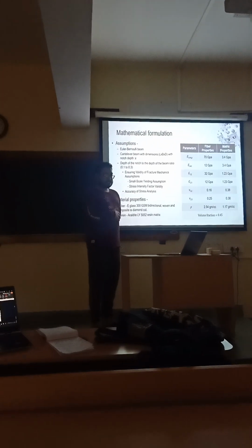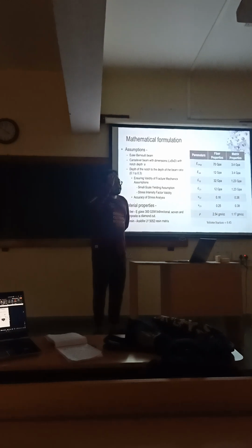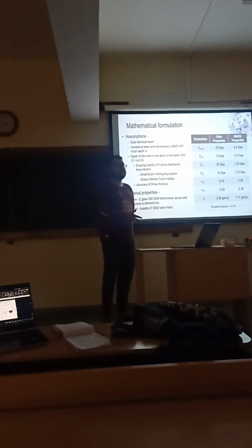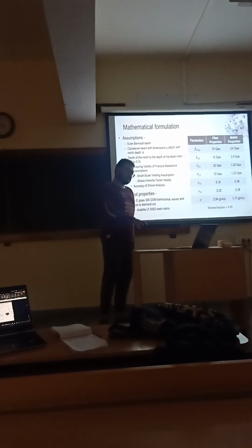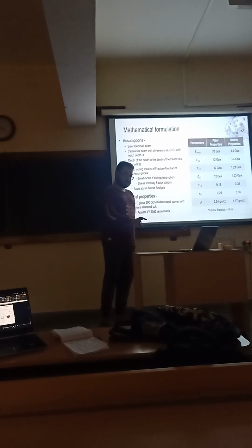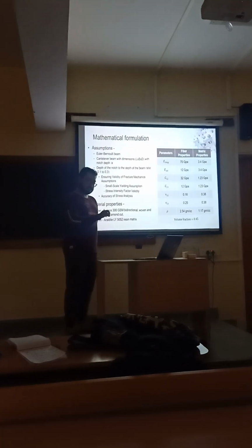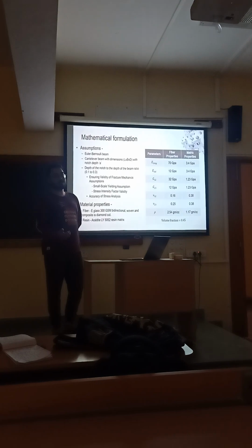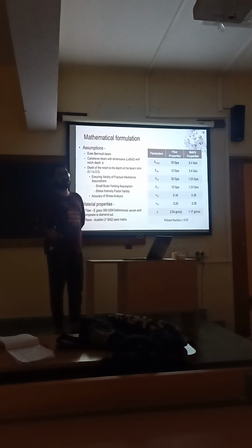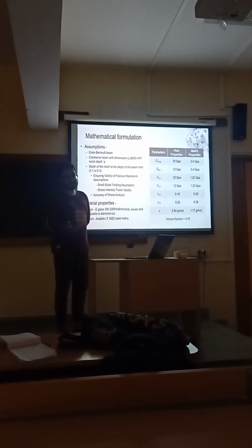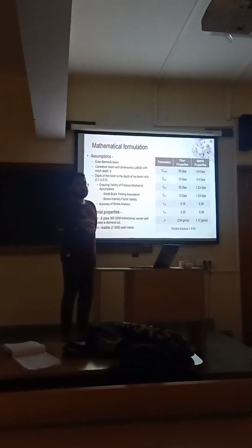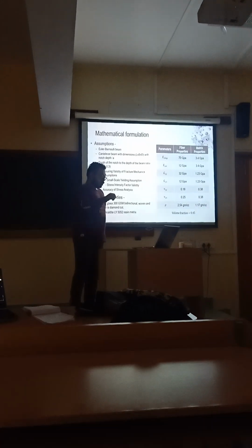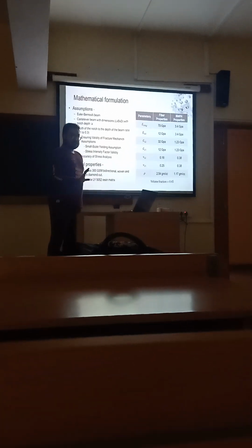And the second thing is the stress intensity factor. The stress intensity factor generally works in this range only. When we are talking about linear elastic fracture mechanics, the stress intensity factor concept is valid only in this framework. If we shift to elastomeric concepts or viscoplastic or viscoelastic materials, there is no such concept of stress intensity factor, because they talk about strain rates, not strains. So these are the assumptions I have taken.